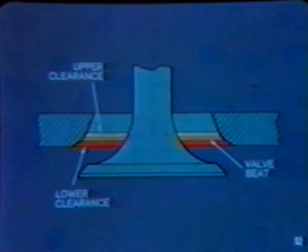The valve seat has three machined surfaces: the seat plus an upper and lower clearance. The clearances are cut to make the seat narrow and to center it properly against the valve face. This provides a better seal and prevents the carbon deposits that could collect if the seat was too wide.